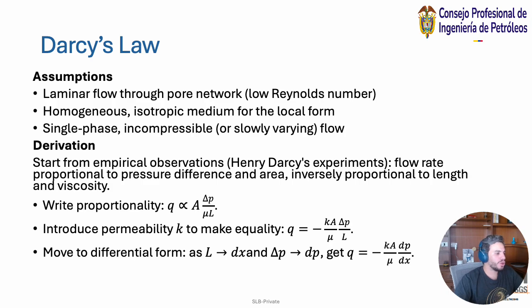And also one thing to note, a takeaway we can say: after each derivation, we'll have these key takeaway points that we want to discuss. Darcy's law is basically explaining to us what the mobility of a given fluid is, and that mobility value you can think of as K over mu. And this is the basis for the diffusivity and the material balance equations, right? We'll talk about the diffusivity equation after we explain how to apply Darcy's law on a radial front, right?